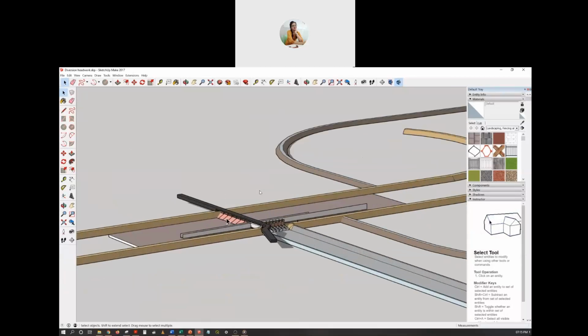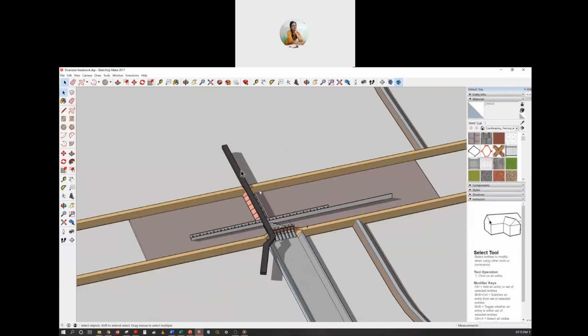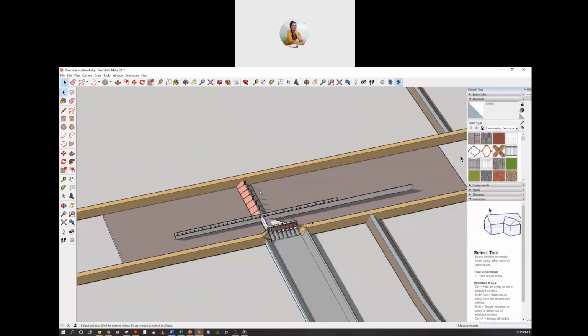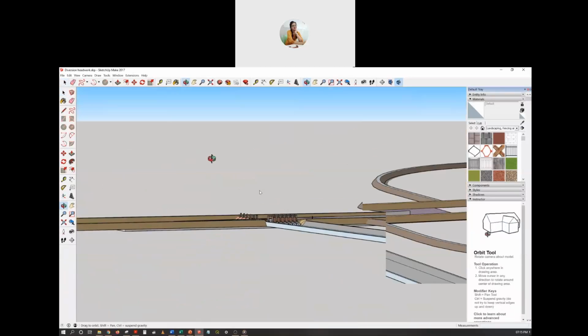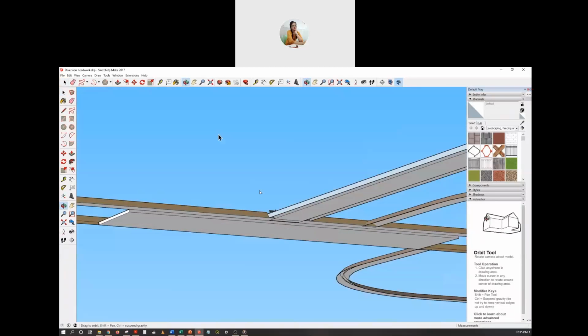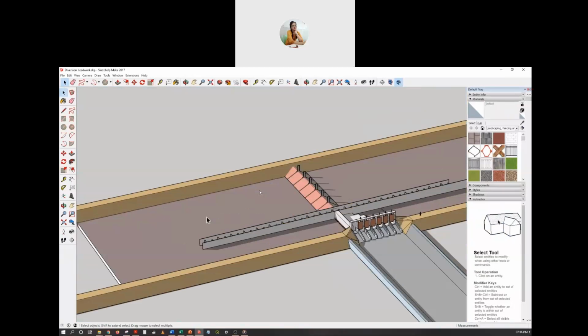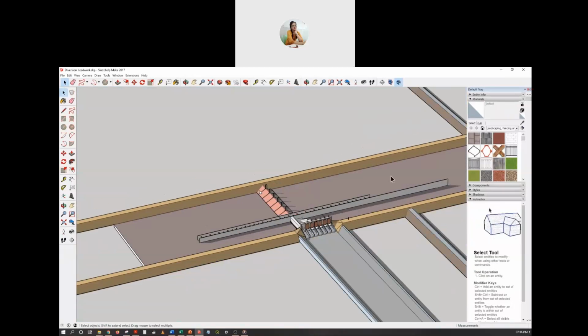One more thing, you see, I've made from here to here, there is a floor. So this is called the weir floor. Now, that means this portion and this portion is not just a river bed. There is a concrete or impervious floor, concrete or masonry floor, which is provided from here up to here.